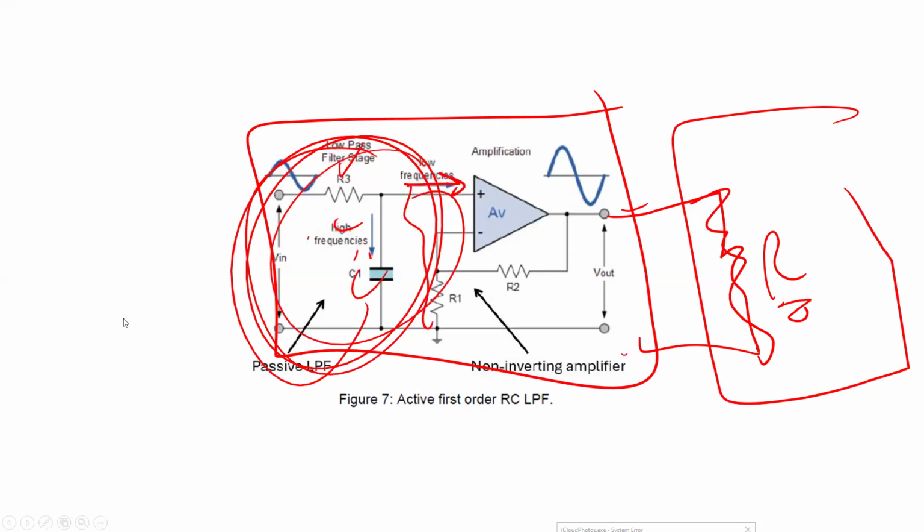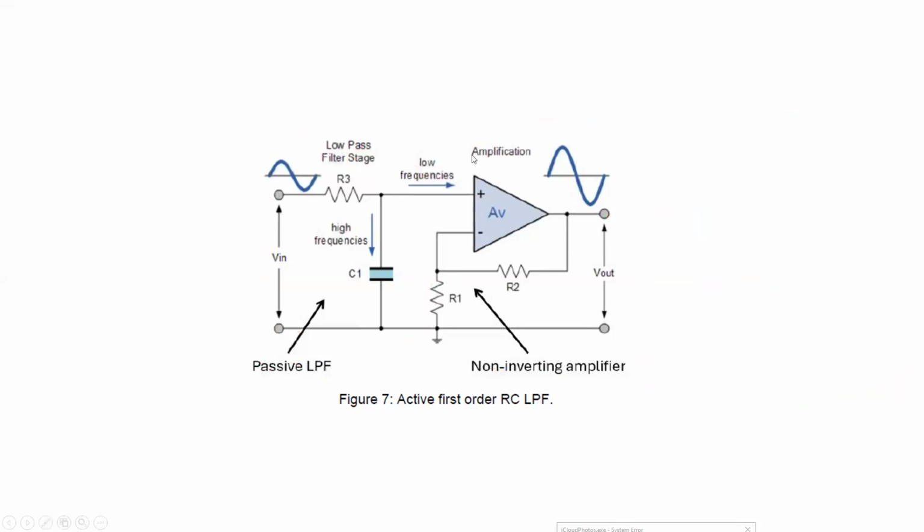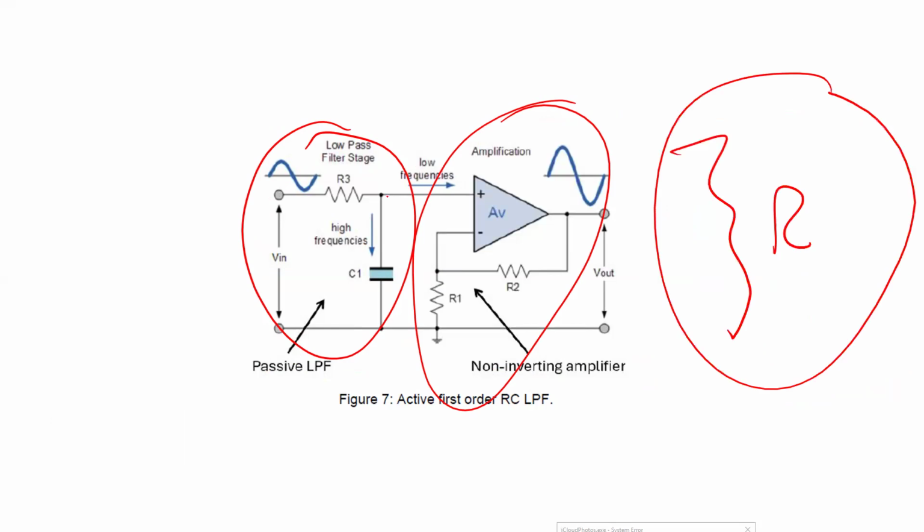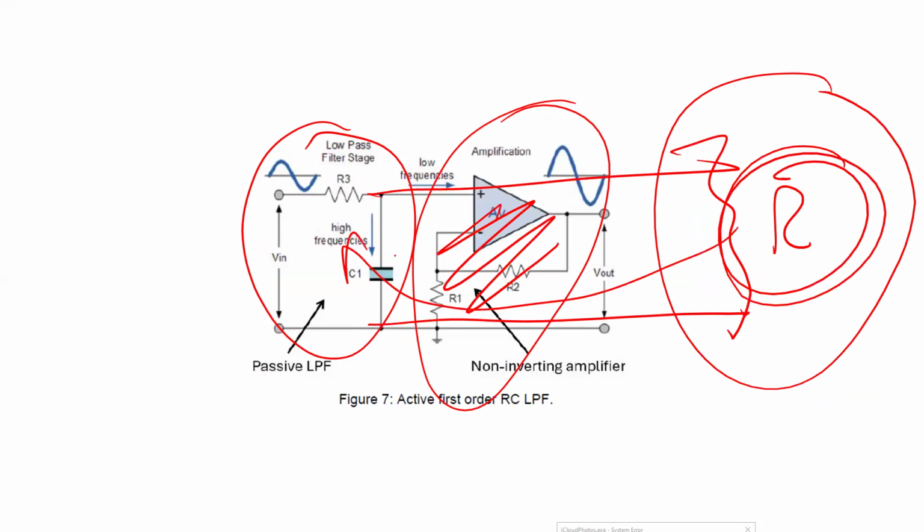So now, in order to summarize, number one, active filters. Active filters use the same thing as passive filters, but here we use an op amp for amplification. Number two, if I connect the resistance R directly, this R is going to be added to the filter's R and C, and it actually changes the cutoff frequency. So we don't want something like that for sure.